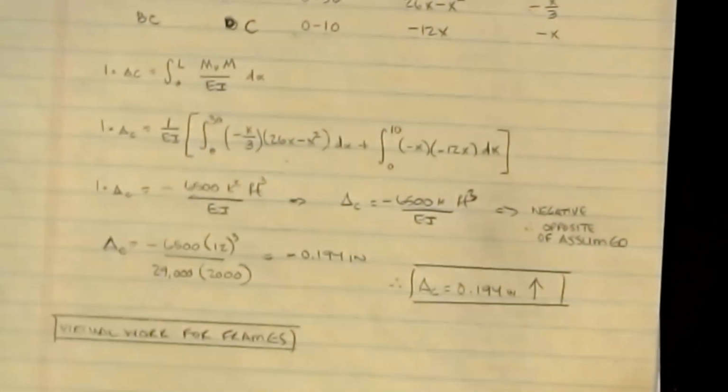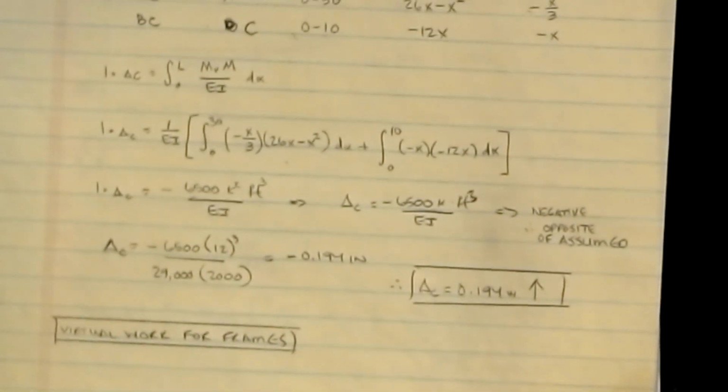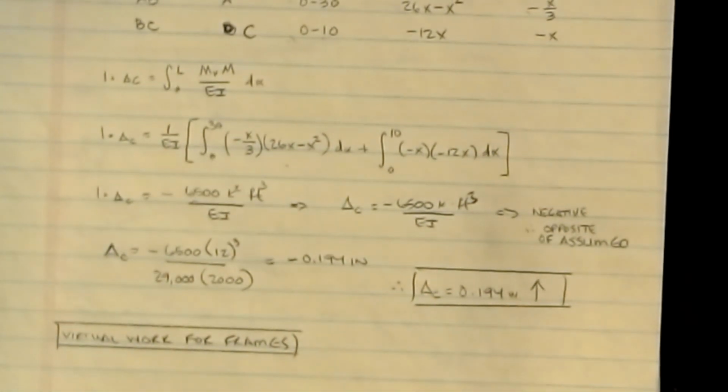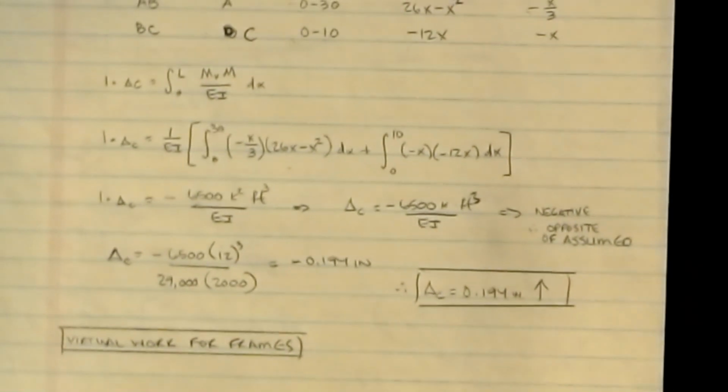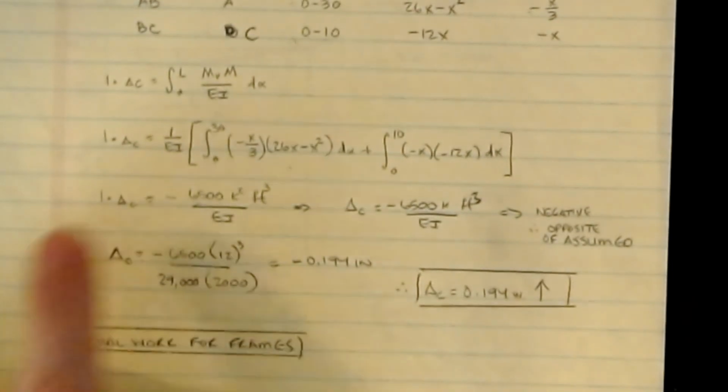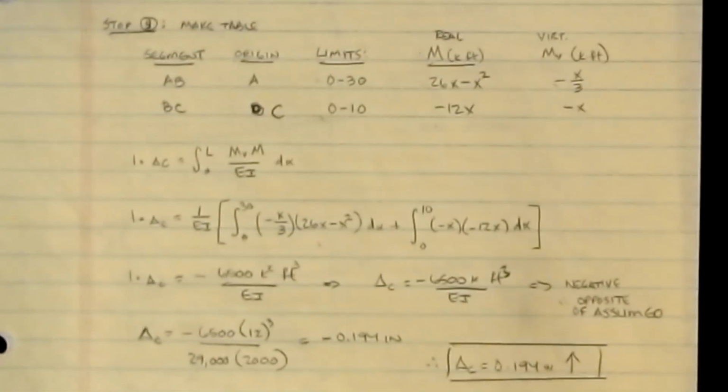That's the method of virtual work for beams. It's pretty easy. All we're doing is tallying up the energy of all of the pieces. In trusses we did it member by member. In this last beam problem, we did the cantilever piece and then the main span piece. All we're doing is an energy calculation for the virtual moments and the real moments on each of those pieces and then doing our computation accordingly. At the end of the day, it all sums up to be contributing to the delta of the real system. That's all there is to it.